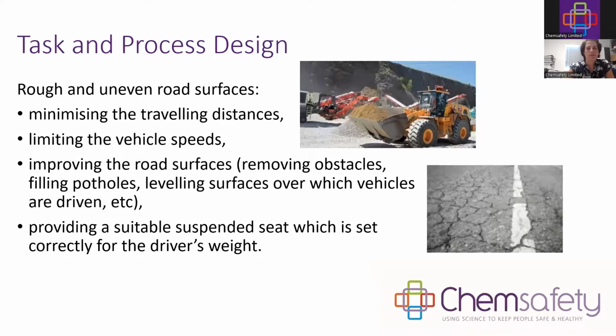And then rough and uneven surfaces can also contribute to high body vibration. So when you have a yard where you're operating mobile equipment and it's hard to keep the road surfaces smooth, say for instance inside a quarry or a pit, take that into consideration while operating the equipment, maybe operate at a slower pace than normal, or be more wary of turning, or accelerate a bit more controlled.